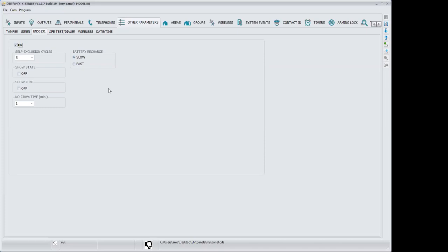There is a special detector. Another important thing, this is a good question. If you use, for example, a voltmeter to check if there is power recharge in the terminals of the panel, you will not measure it, because the charging system of our panel works in PWM. If there is a battery, the panel starts to charge. If you disconnect the battery terminal, the panel stops sending voltage to the terminals.